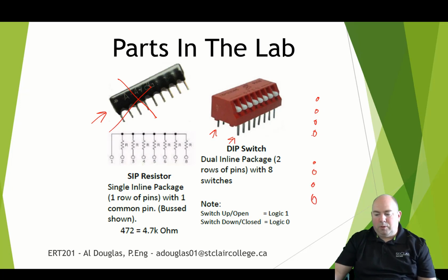We have a bunch of holes on the top side of the board, a bunch of holes on the bottom side of the board, and basically this represents a switch across there. So we have basically 8 switches in a row that give us a nice way to switch things easily on our board. This is what we use to create our logic 1s and logic 0s. That is the dip switch.